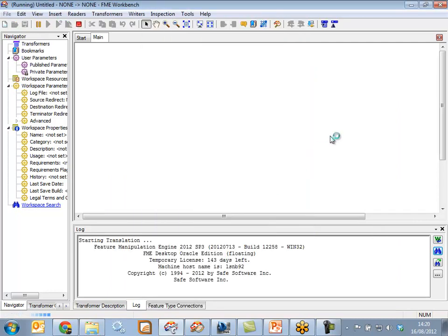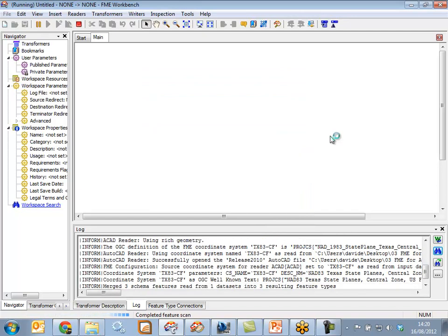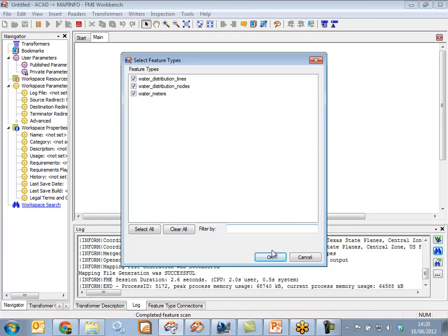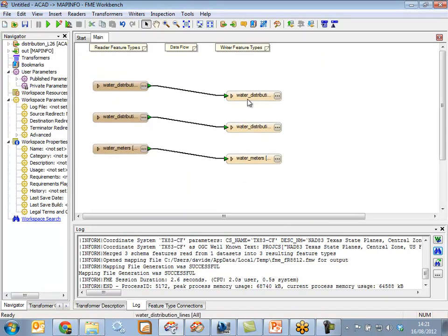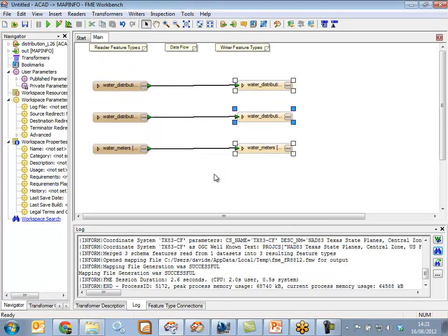We're opening up one drawing file, but inside that drawing file you can see there are 3 layers. Those 3 layers are highlighted here from source to destination. Now FME works with AutoCAD, and it's a file-based data set, which means that inside that one DWG there are many layers. When you write to a folder-based format like MapInfo tab, the 3 layers inside one DWG file will end up as 3 tab files, 1 per layer that was in the drawing file.